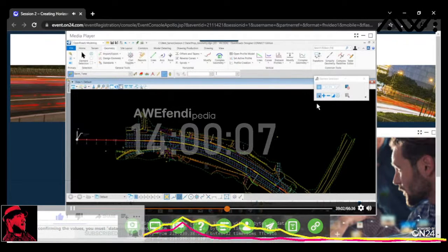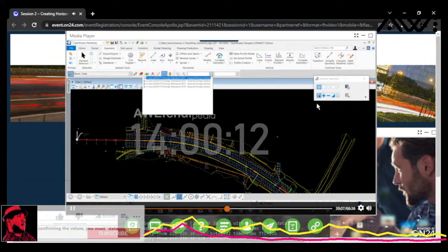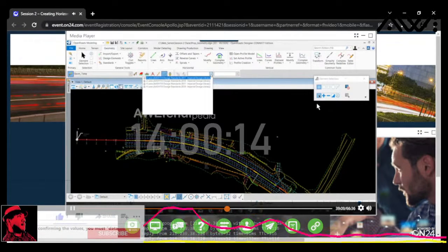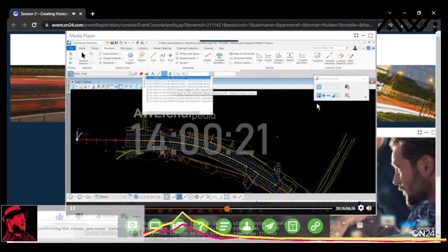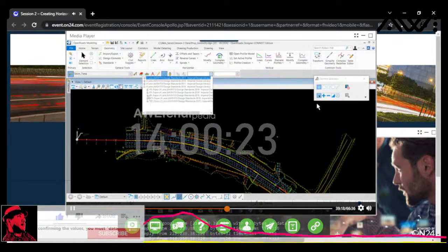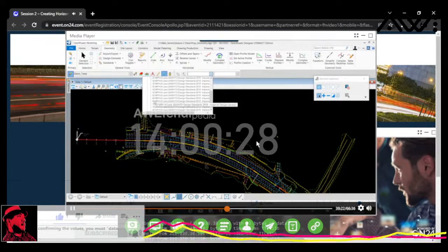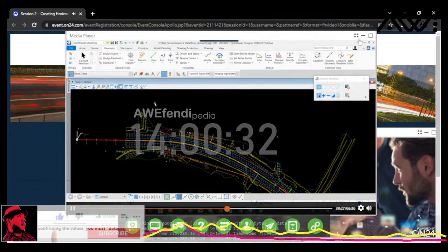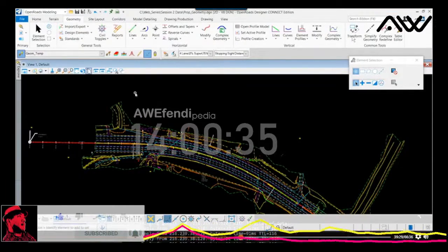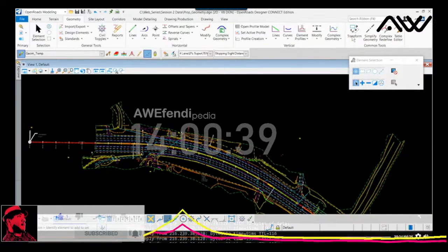And using that toolbar, we're going to be able to select the design speed that we want to use for a particular alignment. So in our case, we're going to use a 4-lane based off of 2018 standards. We know we're going to end up somewhere at an 8% maximum for our super, and we're going to use 70 miles per hour, which is the current design speed. It's posted at 65 for our horizontal alignment. Okay. Now, this is based off of the AASHTO standards for 2018, 70 miles per hour.